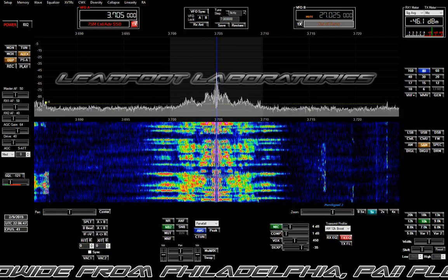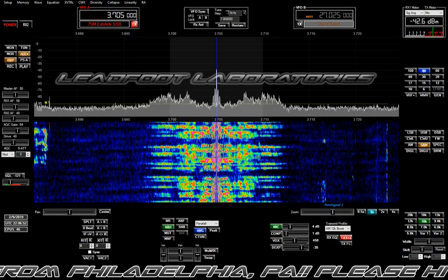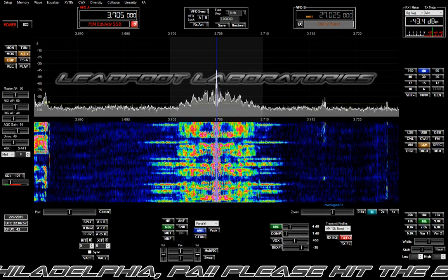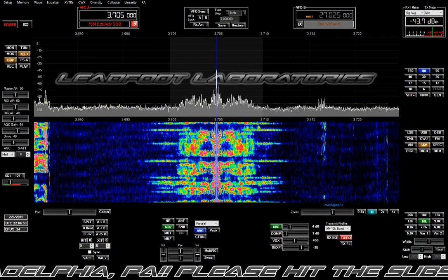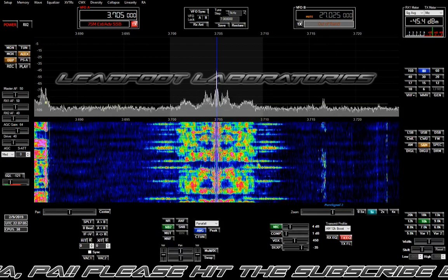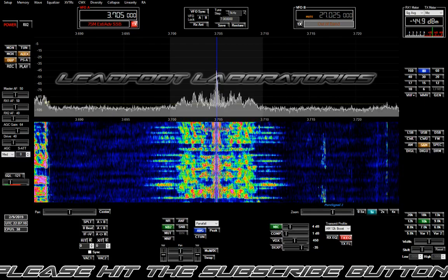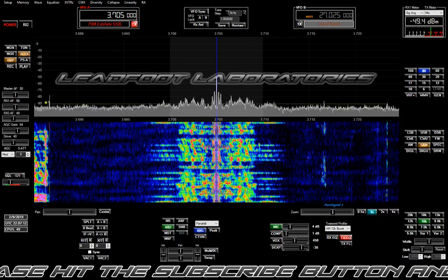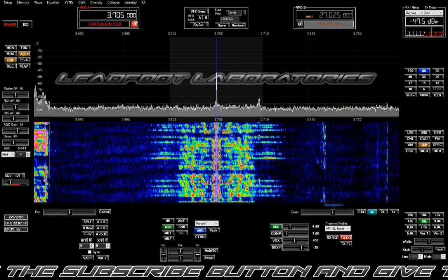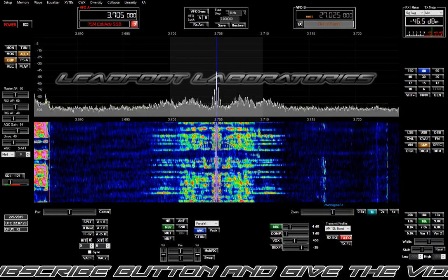And plus, of course, this microphone I use, which is an RE27, has a natural presence boost beginning about, I think, 1 kilohertz. I forgot how many dB it peaks, I think around 3 or 4 kilohertz. So, you add that to the 6 dB boost that I have within those bands, and I'm really boosting the highs. But again, there's a difference between boosting the highs in the mid-band and letting the sibilants, which are really the high-frequency components, pass through the transmitter. So I'd be curious, Frank, as to what you're seeing at your end.